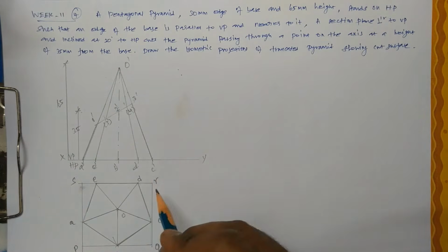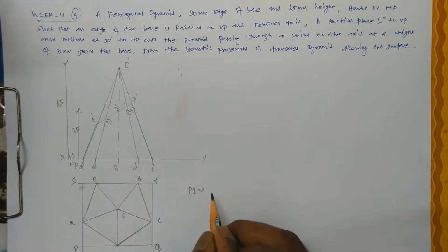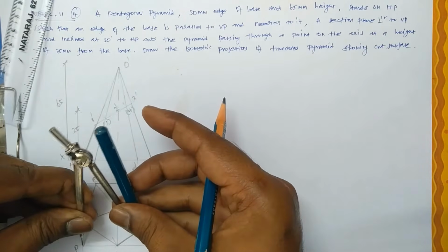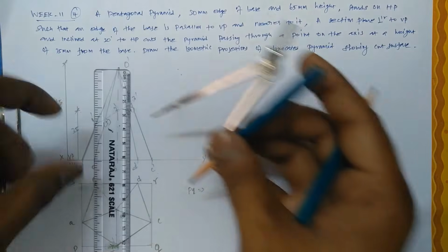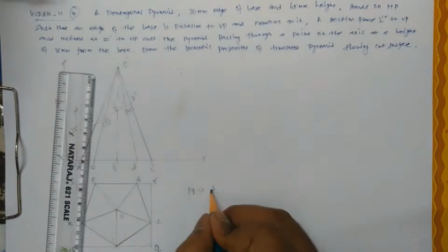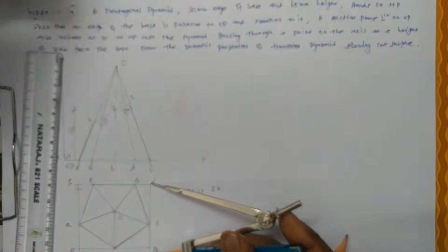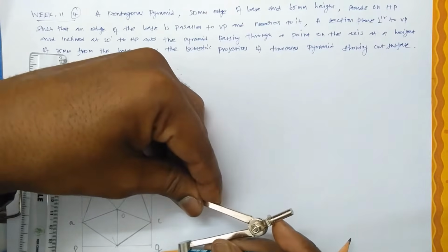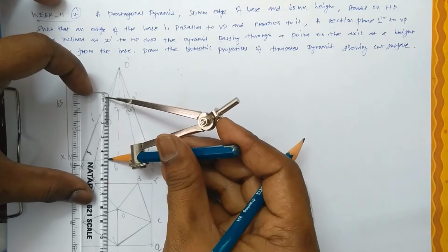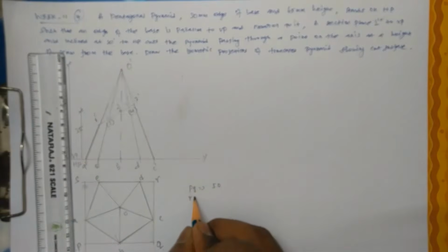Now we just draw the isometric plane. Before that, let us measure the edges distance PQ. Let us measure, and then we just foreshorten it. P to Q is about 5.1 or 5. Let it be 50, and P to S or Q to R all are equal. QR is 45, it's almost coming. See, parallel direction or equal.